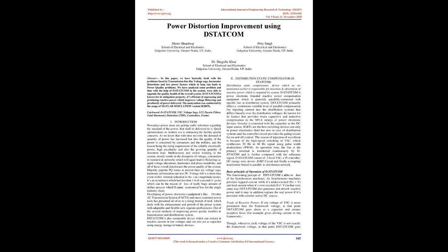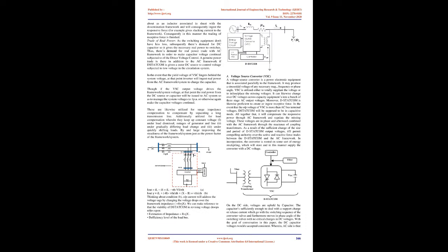2. Distribution static compensator, D-STATCOM. The distribution static compensator is a device which, as we mentioned earlier, is responsible for injection and absorption of the reactive power required by the system. D-STATCOM is a power electronics based reactive power compensation device which is generally connected in parallel with a specific bus in the distribution system. D-STATCOM primarily offers a continuously variable level of parallel compensation, by injecting current into the distribution system that varies linearly with the distribution voltages. It is known for its feature that provides both capacitive and inductive compensation up to the MVA ratings of the power electronic devices.